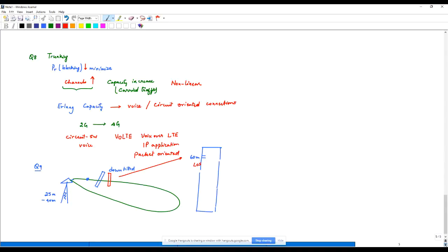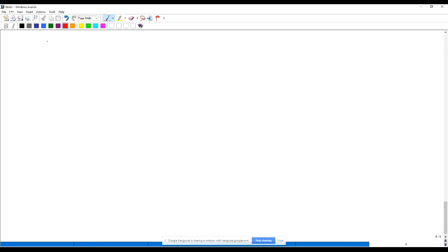Now, another question from Chandra Sharma: how much coverage will penetrate if we are in GSM technology? Okay, so here is another very important one. Signal penetration into buildings. Signal penetration. This is a very, very important one. Now, regardless of whether we're talking about GSM or LTE, there is substantial loss when you have to penetrate walls, when you have to penetrate any metallic framework, like when you're inside an elevator.